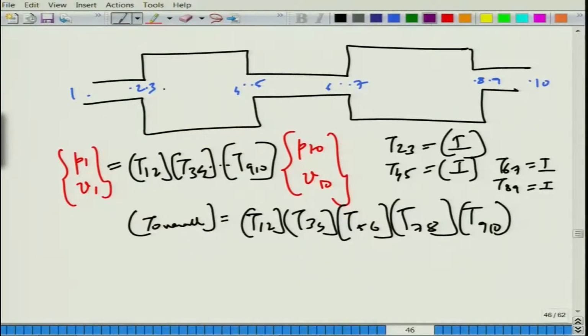What exactly am I trying to say? What is the message that I am trying to convey? For a typical commercial muffler, you typically have two muffler shells attached to each other, one upstream and the other downstream, and internally you can have a very complicated structure here and a very complicated structure here. But still the wave propagation path is unique from upstream to downstream.